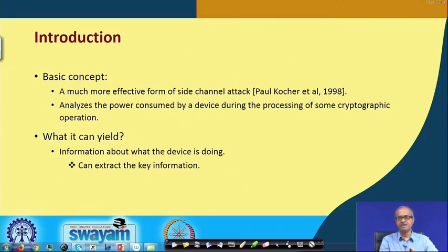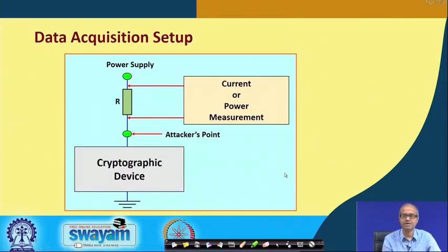If I can measure that, that will give me information about how much power is being drawn by that device. Okay. So, this kind of analysis can yield information about what the device is doing, and just like timing analysis, here also we can extract the key information. Let us see this in a little more detail.